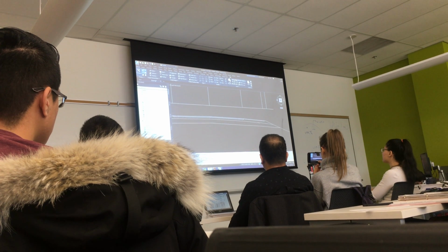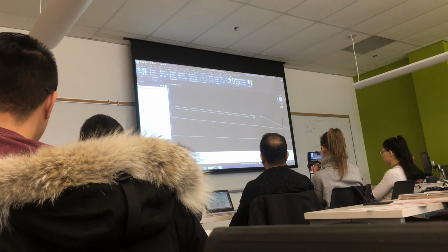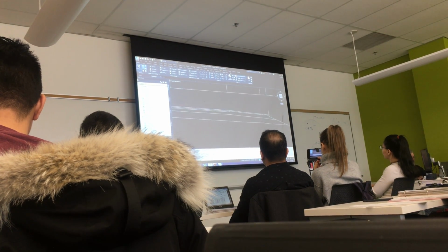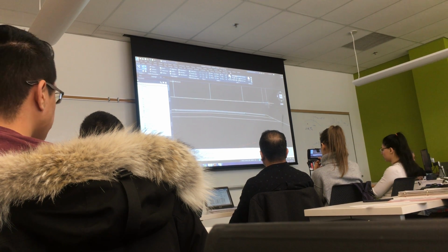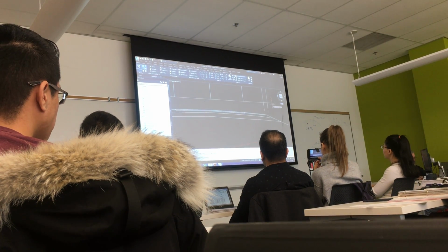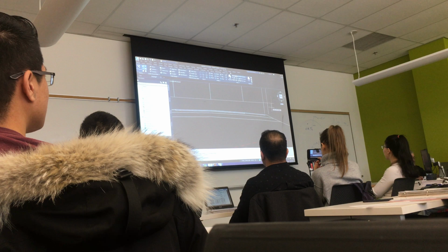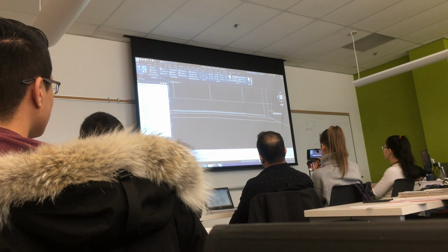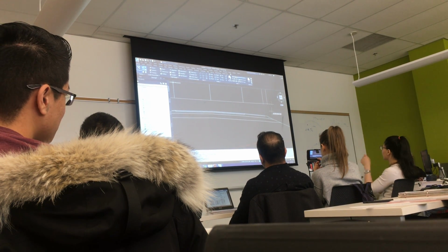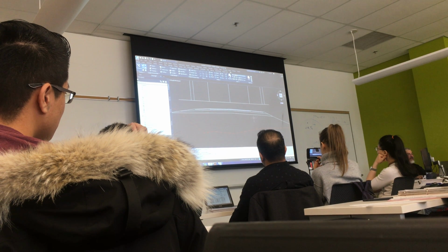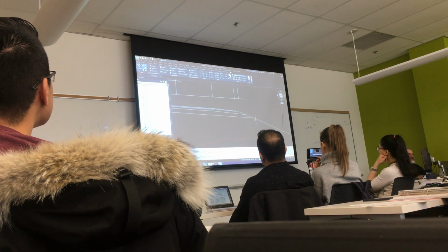Then there's a paved shoulder. Then there's the rounding between here and here, right? Look at the dimension lines. If you bring these back down, right, there's your rounding zone. So the shoulder ends there, but the plane of the shoulder extends across at 6% to the middle of the rounding. So now you can clearly see this point is above the ground.